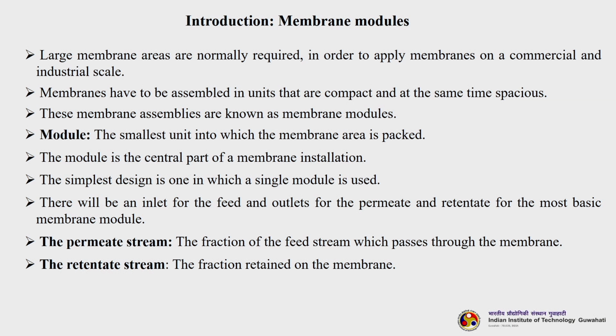The simplest design is the one in which a single module is used. There will be an inlet for the feed and outlets for the permeate and retentate. That is the most basic membrane module that is possible. The permeate stream is the fraction of the feed stream which passes through the membrane, and retentate is the one which is retained on the surface of the membrane.